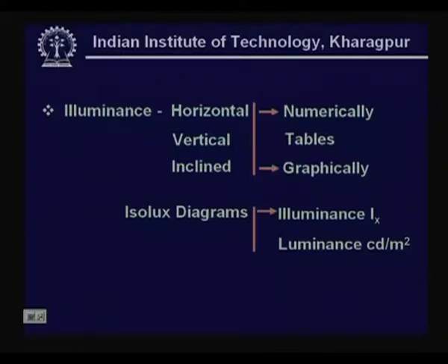So what do we have? We have the illuminance, which is a very important thing. Depending on the nature of the work plane, horizontal plane, vertical plane and sometimes inclined plane, this data is available in the form of tabulated numerical values, or graphically in the form of isolux diagrams.